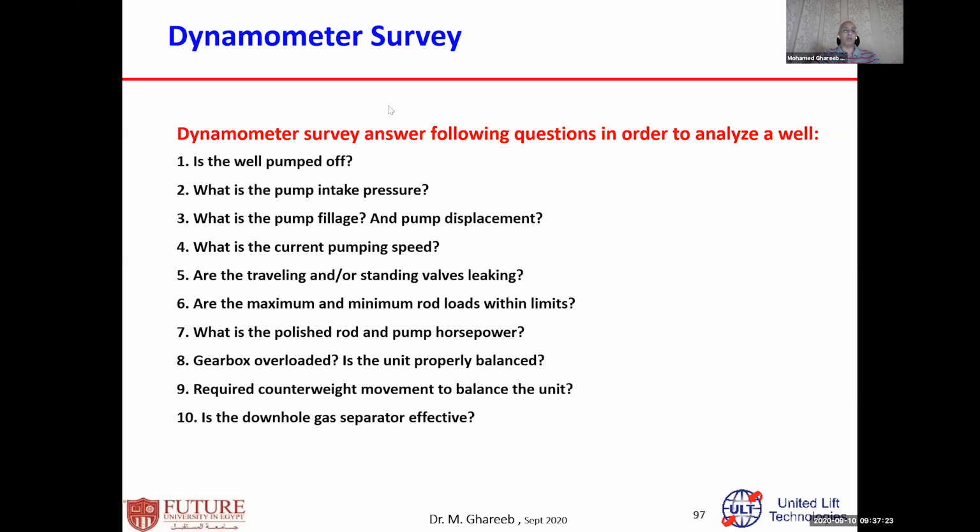But remember, what is a load and what is a pressure? Pressure is a load, it's pounds per square inch. The load over the pump, which is lifting the fluid only, acts over the cross-section area of the plunger. Then the maximum fluid load in the pump, if I divide this fluid load by the cross-section area of the pump, gives me the pump intake pressure, the pressure which is lifting from the sand.